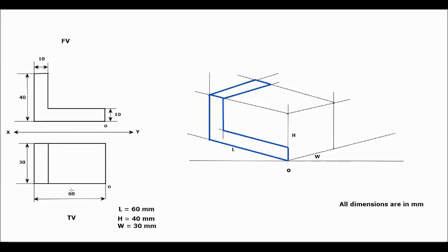Now if you observe the top view, the complete rectangular surface is visible after this small rectangle. So it means that this vertical slab we have to draw, and then for this horizontal slab portion, this rectangle is shown in your top view. So for completing your object, now we'll use a projection line first.